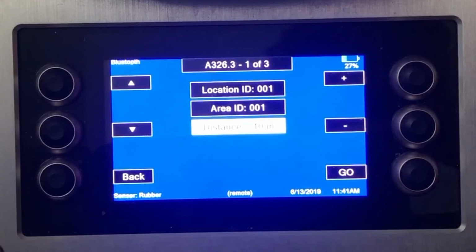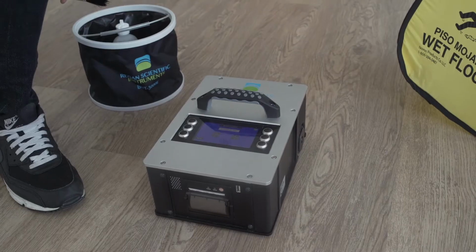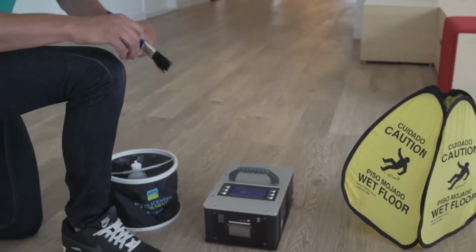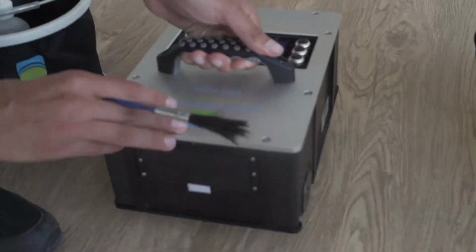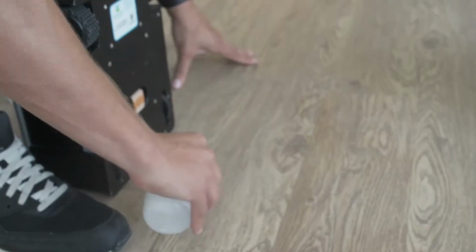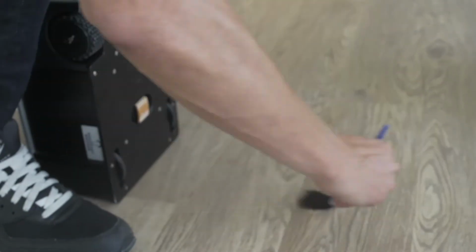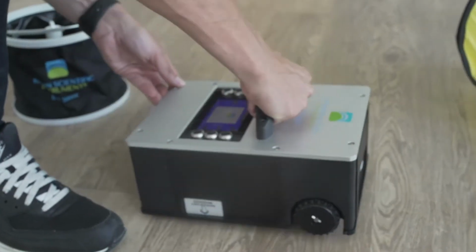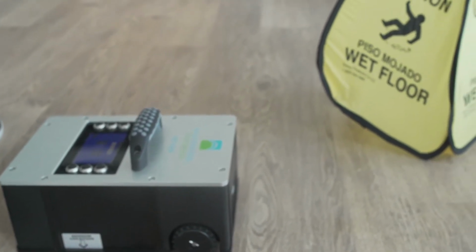Your screen will show 4 boxes for each of the dynamic measurements that you'll take at each test sample. Take your first measurement, then turn the bot 180 degrees and redistribute the SLS solution. Then, take the second measurement over the same wetted path. After the second measurement, remove the SLS solution from the floor's surface with a cloth or paper towel. Then, wet a new path with the SLS solution 90 degrees from the previous one. Take the third and fourth measurements along the new path in the same fashion as your first and second.